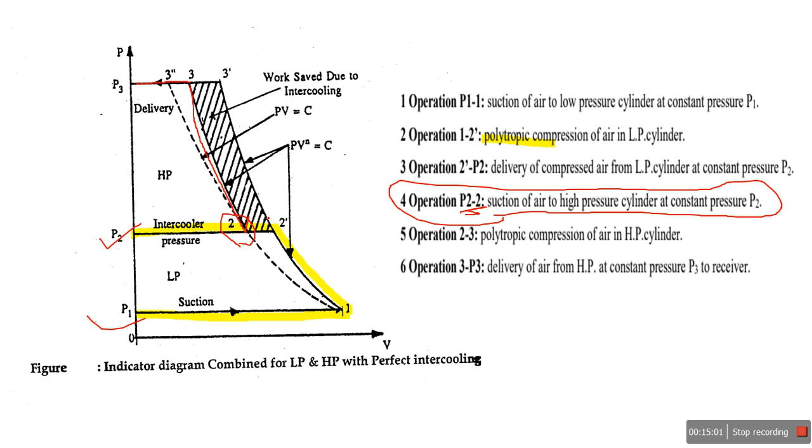Advantages, I now summarize this lecture. The power required to drive a multi-stage compressor is less. A multi-stage compressor has better mechanical balance. The pressure range due to multi-staging remains within a desirable limit, so losses due to air leakage are less. The temperature range due to multi-staging remains within desirable limits. Due to multi-staging, volumetric efficiency for a given pressure ratio improves. Okay, thank you.